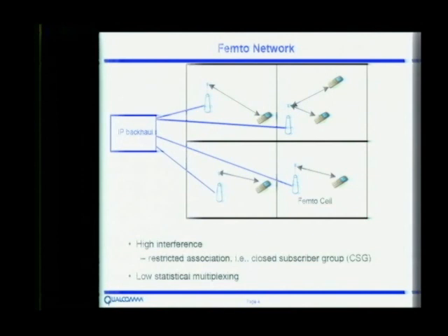In fact, with the duty cycle of these femto cells, it's possible that you hit your QoS with a higher probability here than you would in a macro network. And at high loading, you're not likely to get the best QoS. But the level of reuse of the spectrum that you get with this kind of deployment is just so high.